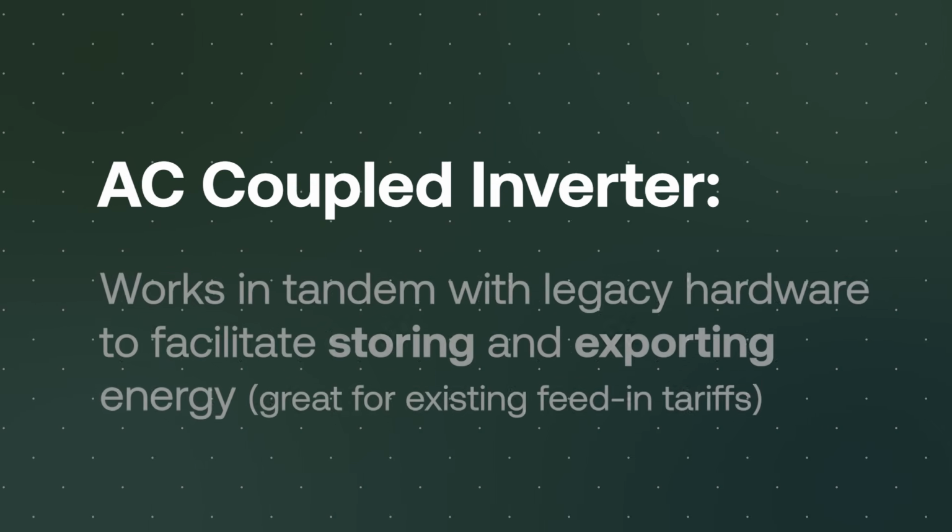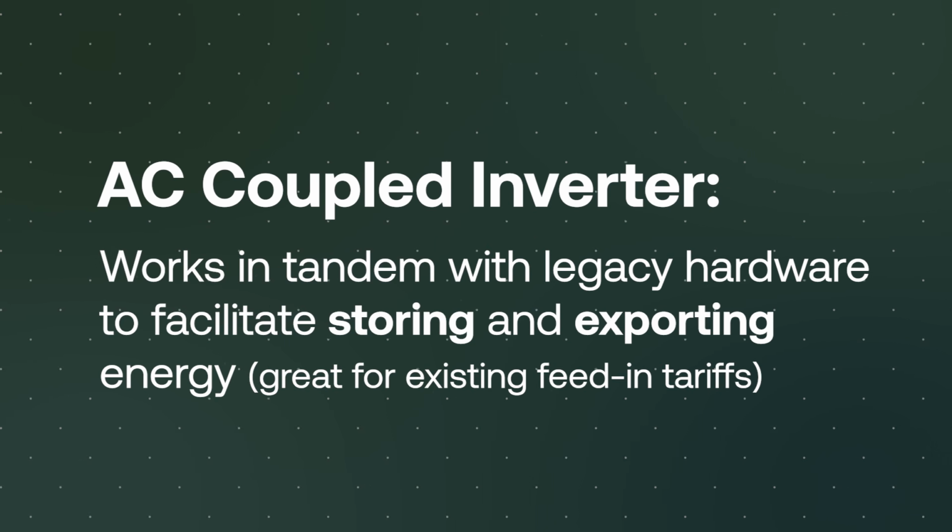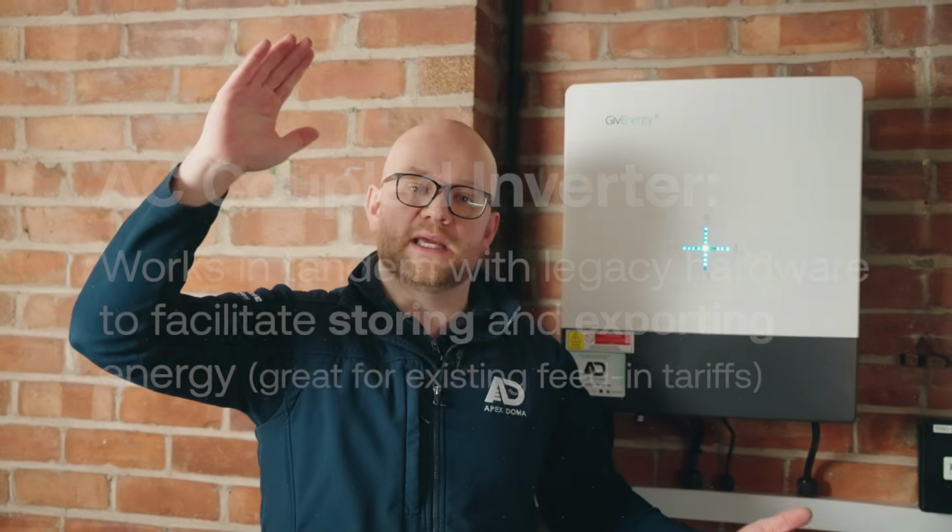The next type is a thing called AC coupled. Now this is brilliant if you've already got a solar system. Let's say you had a solar system fitted a couple of years ago, or you had a system installed under the existing feed-in tariff and you don't want to sacrifice any of those feed-in tariff payments. The AC coupled will leave the existing inverter alone. It tracks what your existing solar generation does, gives you this information on an app, and can store and charge and discharge the energy in real time. Essentially, you have two inverters both working in tandem.